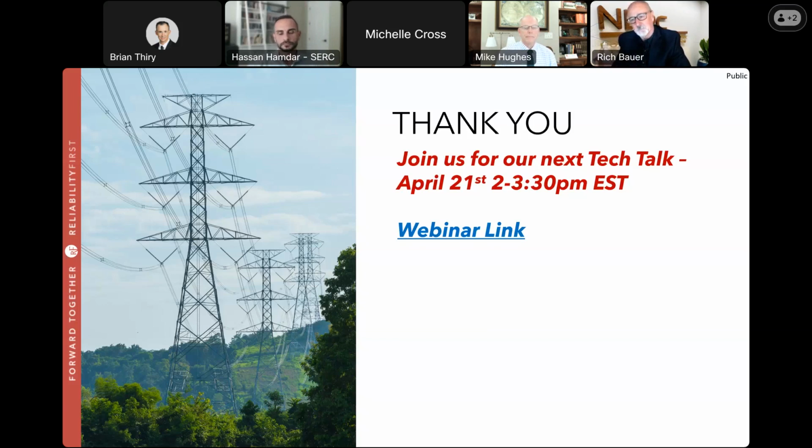And we'll probably talk more about that reconnection of load, because if you go away and then you come back very quickly once the fault's cleared, that's okay. But if you go away and you're gone for a few minutes and then you come back very quick with your whole load, that's a real problem for the BA. So at the end of the day, you've got to have those types of procedures in place where you control that load coming back. So hopefully that answers that.